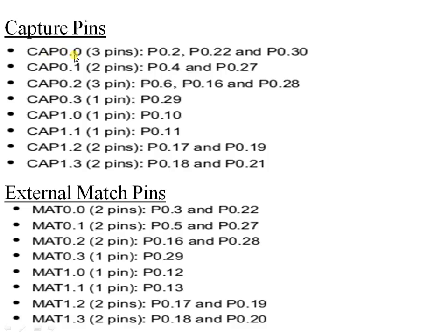So CAP0.0 indicates timer 0's capture channel 0, CAP0.1 indicates timer 0's capture channel 1, CAP0.2 indicates timer 0's capture channel 2, and CAP0.3 indicates timer 0's capture channel 3. Under each of these categories you can see multiple pins, and you have to select any one of these pins to work as the capture pin. We'll discuss those things.